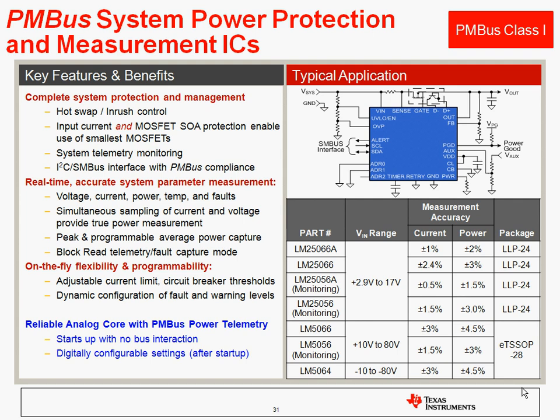And that's primarily an analog circuit, but it does have a PMBus digital interface capability so that you can program the warning thresholds and you can monitor with high accuracy the current, the voltage, the power, and the temperature, and all the fault conditions out of this part. So again, a hybrid of an analog loop with extensive power telemetry and some programmability.